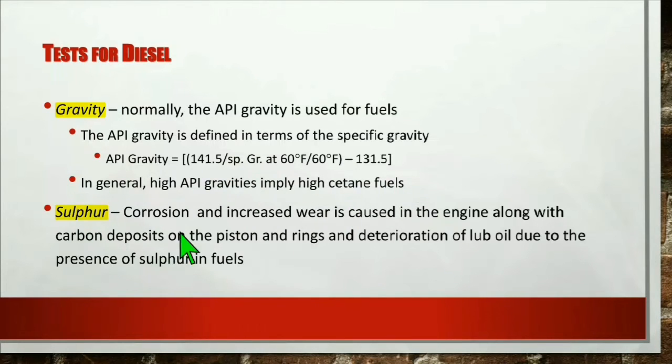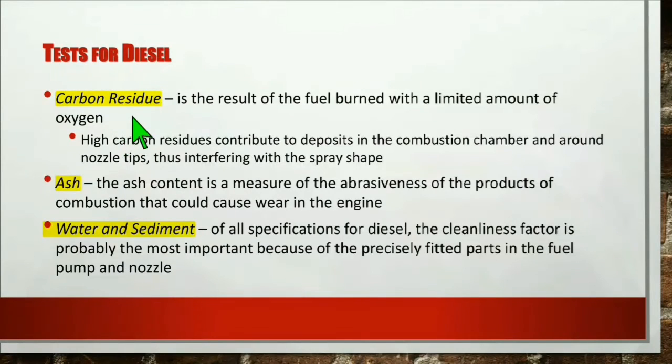Sulfur. Corrosion and increased wear is caused in the engine, along with carbon deposits on the piston and rings or deterioration of lube oil, due to the presence of sulfur in fuels. Carbon residue is the result of the fuel burnt with a limited amount of oxygen. High carbon residues contribute to deposits in the combustion chamber and around nozzle tips, thus interfering with the spray shape.